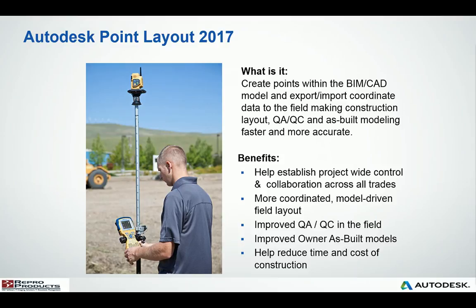We can take our new design and use Autodesk Point Layout to place the new design points of the building, or say for example the column grid, and then use those points to put into a total station and generate those new design points out in the field.